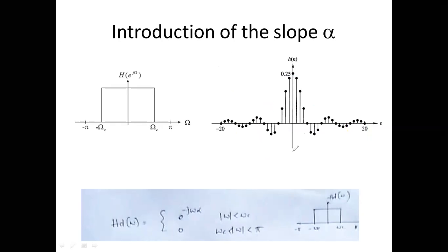Now this whole thing of picking the finite values is called windowing. Your impulse response had an infinite number of values, but you make sure that the response is symmetrical and you pick finite values from the center, on the left and the right side. The entire process is called windowing.